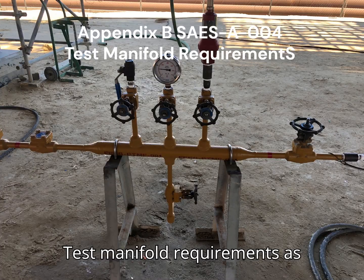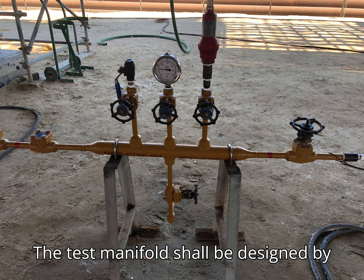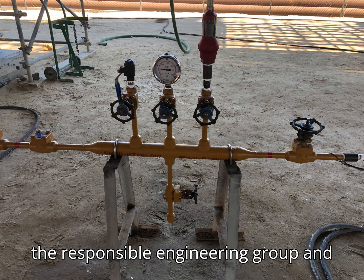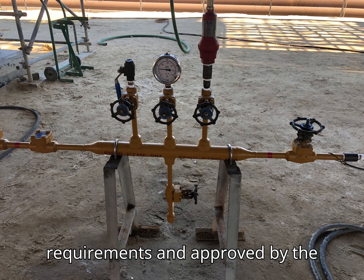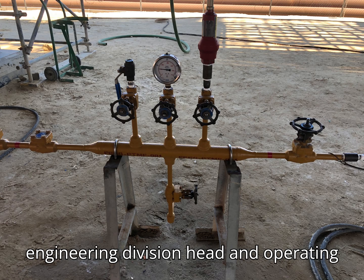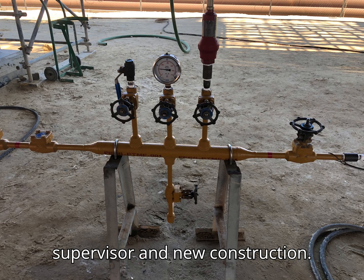Test manifold requirements as per Appendix B, SAES-A-004. The test manifold shall be designed by the responsible engineering group and constructed to meet the minimum system requirements, and approved by the engineering division head in operating facilities or the responsible PQM/senior supervisor in new construction.